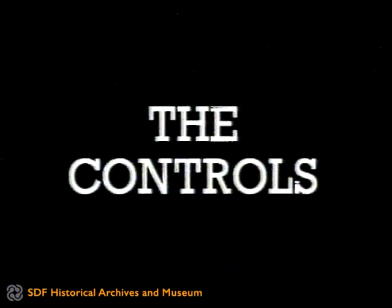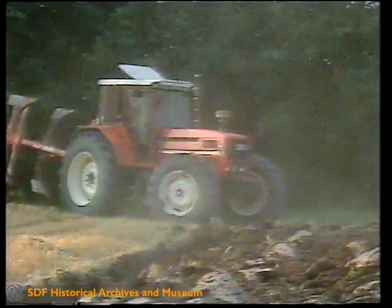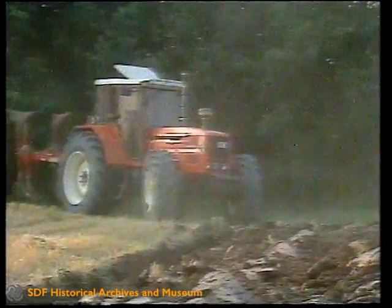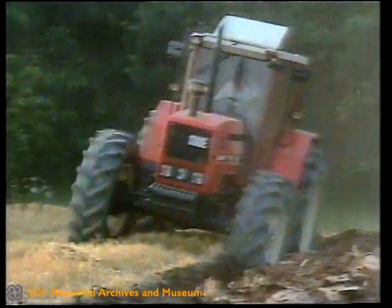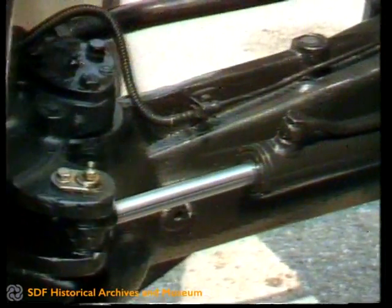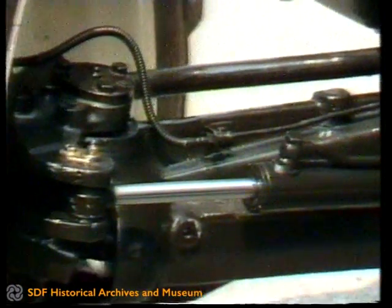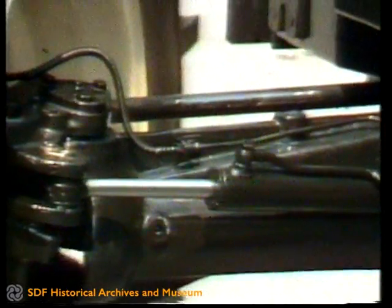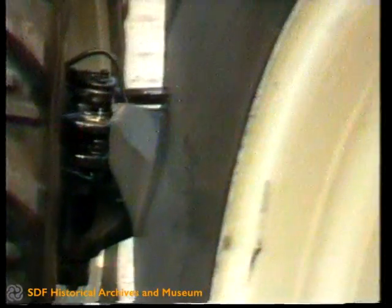The controls. Comfort is also achieved by reducing the effort which the driver has to exert in order to operate the various controls. For this reason, on all our models above the 50 horsepower, we have brought into general use the hydrostatic type of control, clutch and brakes, and hydraulic servo controls, steering and PTO engagement. For easy, precise steering, particularly for road transport, we use a reactive type of hydrostatic steering, which eliminates the irritating drift effect associated with some types of hydrostatic steering, and the steering wheel automatically returns to the central neutral position after a turn.